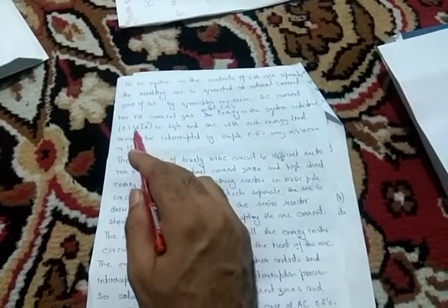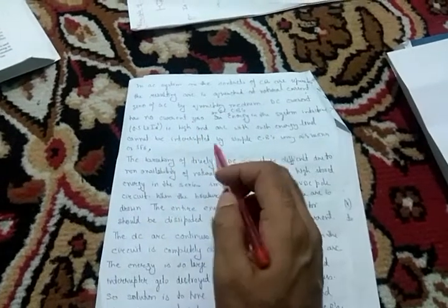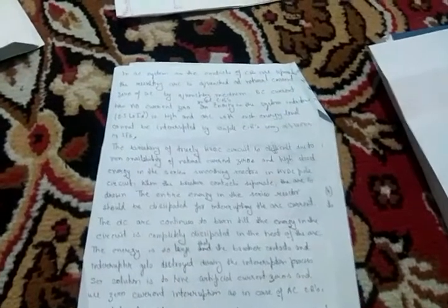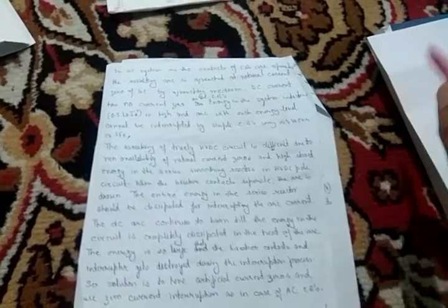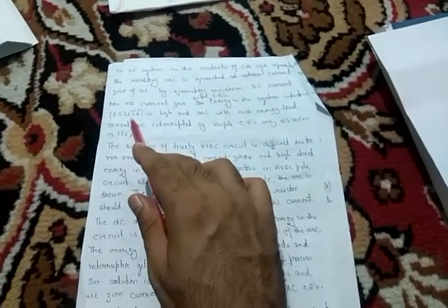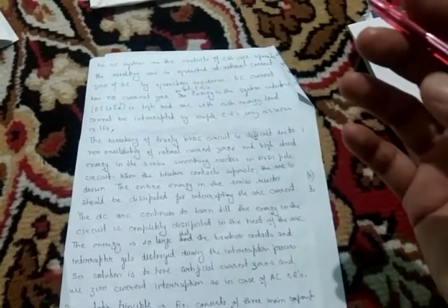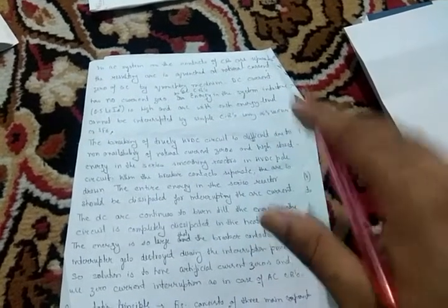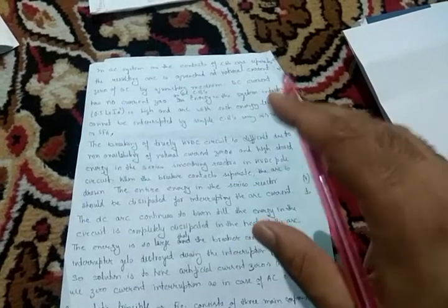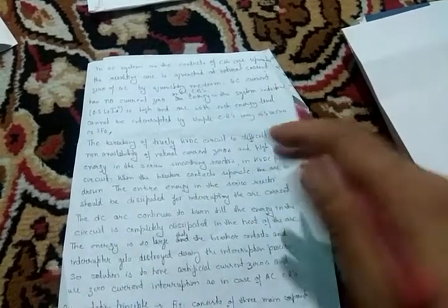We know that I is very high. We have an inductor of large size, so huge energy is stored in this inductor. And an arc with such a high energy level cannot be interrupted by a simple circuit breaker. Means a simple air, vacuum or SF6 circuit breaker cannot interrupt it because the current is at a constant value. Moreover, the system inductance has very high energy, which is given by half of L I square. So we cannot suppress the arc by interrupting. We cannot interrupt the current by using such circuit breakers.